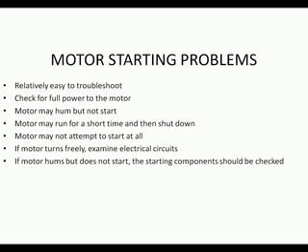In this case, we have a shorted winding, which is actually touching the frame of the motor. So here, regardless of what terminal I take the reading on, if I put one lead of my ohm meter on a terminal and one lead on a clean casing of the compressor or motor, I'm going to have a reading. Well, if I have a reading, I'm going to have current flow going to the ground.